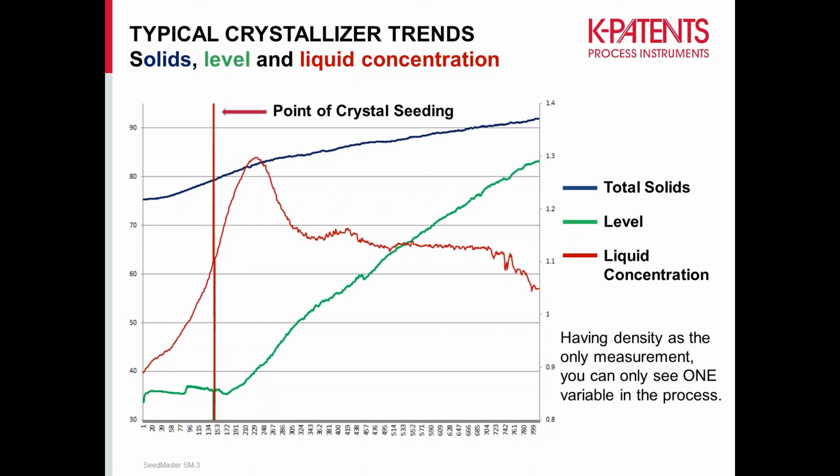So continuing on the PM, knowing the process medium. Is that material liquid or gas? A refractometer only measures liquids, where Coriolis can be both liquid and gases. Are there any suspended solids, like in a crystallization application? And is it desirable or undesirable to factor those suspended solids into your measurement? Do you want to know the liquid portion only, or total solids, liquid and the suspended solids?